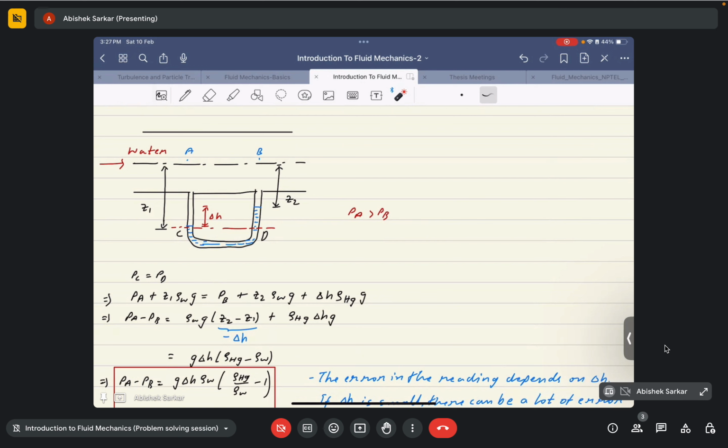You can also use the principle of manometry to measure static pressures in a liquid container, or in the case of a venturimeter as well. These are the places where the manometer is useful. Are you clear regarding the concept of manometry, like how the derivations are done to measure the pressure difference between these two points?